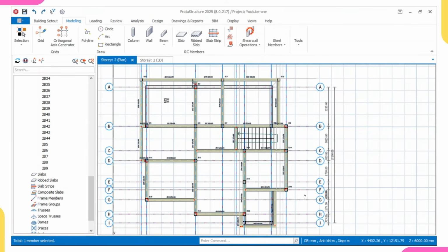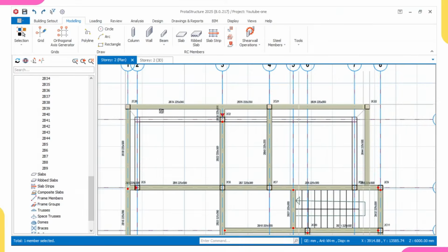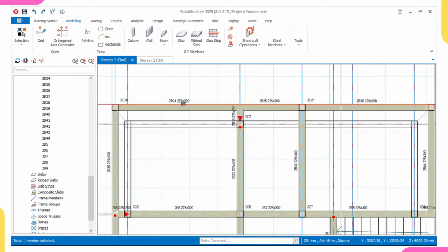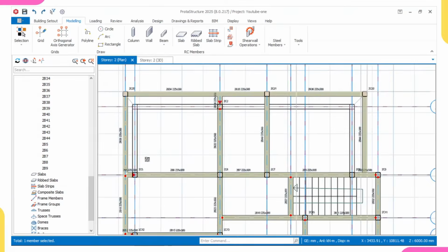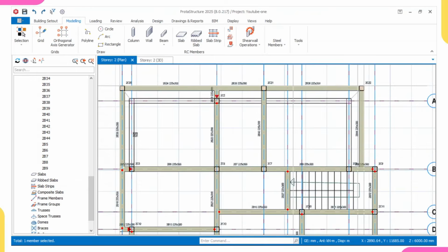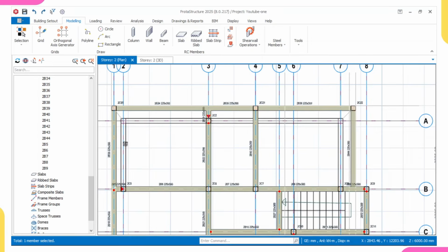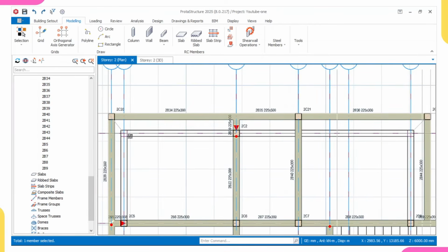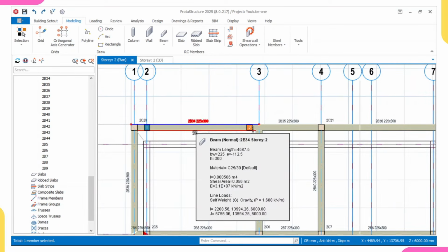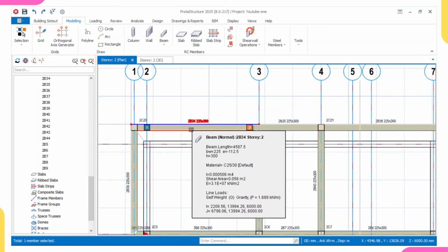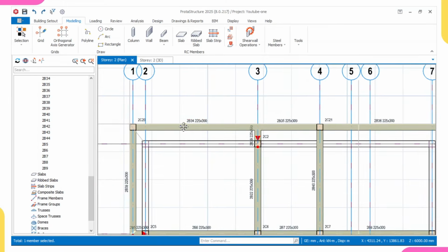let me say something. If you can remember, in story 2, we did not do anything like fixed end moment, summation of moment equal to 0. The reason why we did not do it is because I know that it will pass. I've done a lot of design, and I've always been getting 2Y16. So that's why I did not bother doing it. Even the application of parapet load, I did not bother applying it because I know I'll still be getting 2Y16. Okay, in fact, let's do the parapet load.